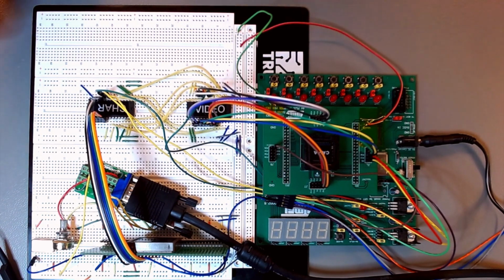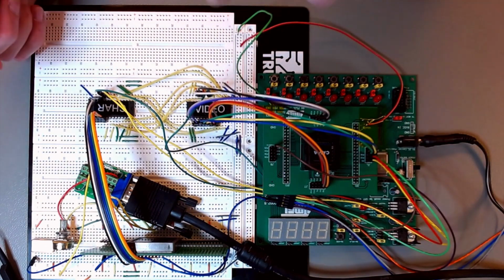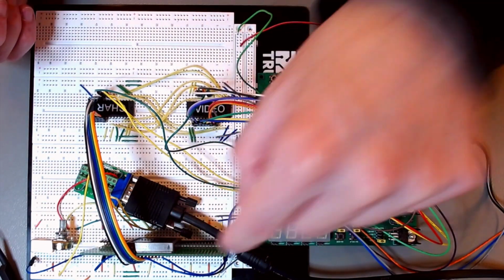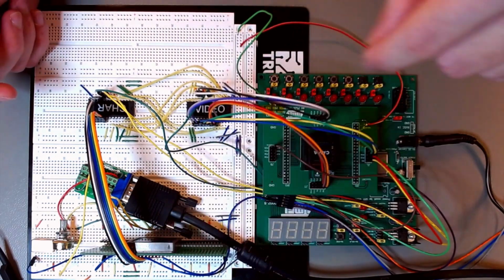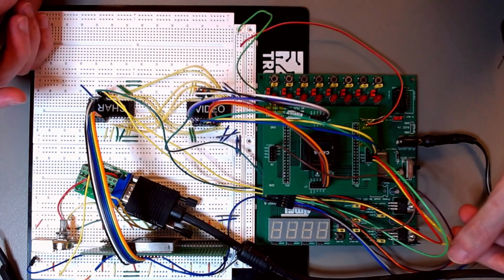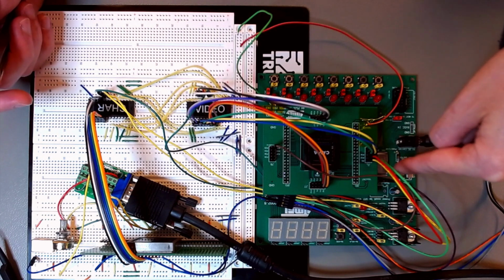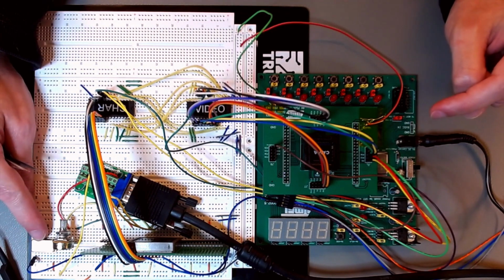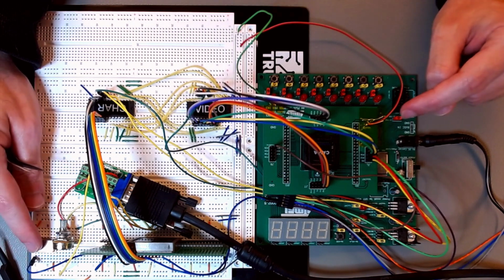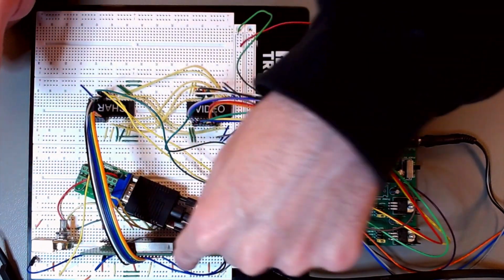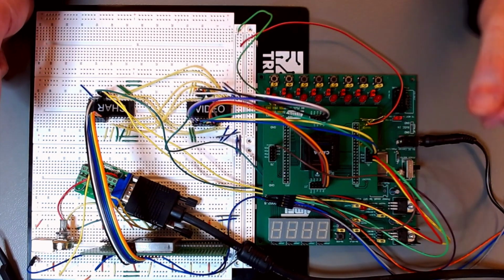Just to give you an overview of what's happening, CAVIA is on the development board because I don't have the right socket, the right adapter like this one, yet. I'll get it in a few days. SCANC is here. The clock for CAVIA comes here from SCANC. I'm using this oscillator here, 25.175 megahertz, which is the right frequency to generate the clock for SCANC, and SCANC in turn generates a masked clock, or a CAVIA clock, for CAVIA.